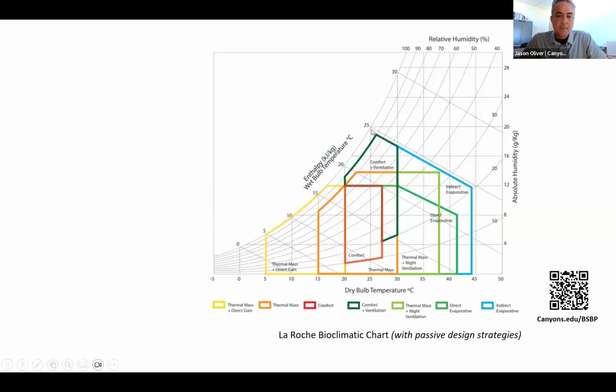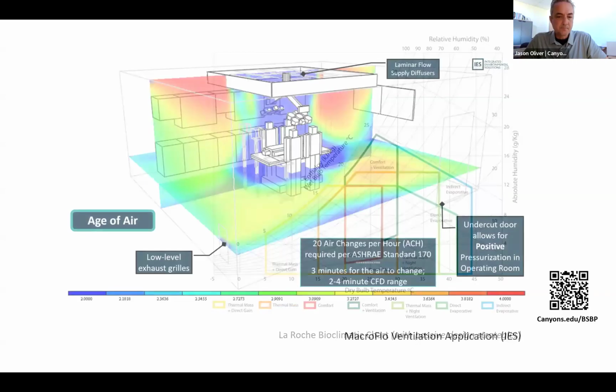And that's really important for a variety of reasons. If we need to naturally ventilate a space, we have a broader comfort range for the conditions inside the space, that people are more tolerant of a broader temperature range, a little bit broader humidity. And so by simulating that, it allows us to verify or confirm that natural ventilation would be an appropriate and a code compliant method for a building project.